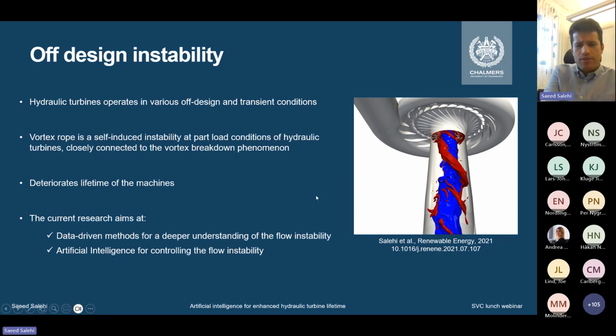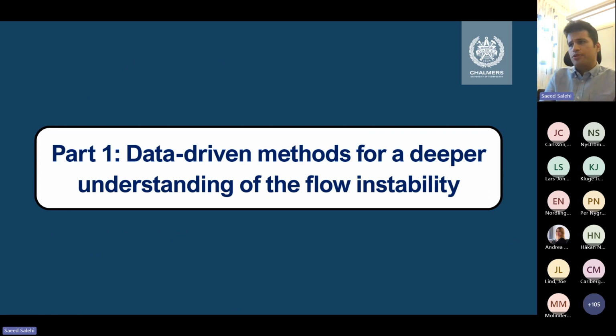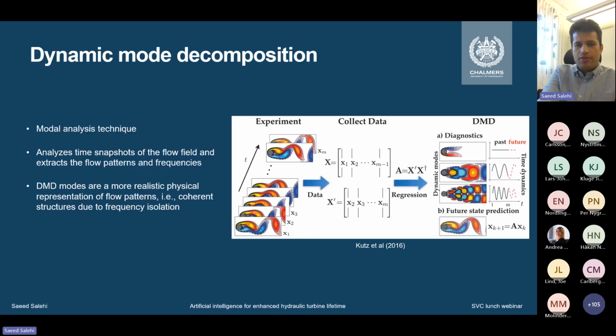First, I will start with using data-driven methods to get a deeper understanding of this instability. In this research, I use dynamic mode decomposition, which is a modal analysis technique that analyzes time snapshots of a flow field to extract patterns, frequencies and coherent structures. Many people are familiar with POD, proper orthogonal decomposition, and DMD can be seen as somewhat similar to POD, but they are fundamentally different.